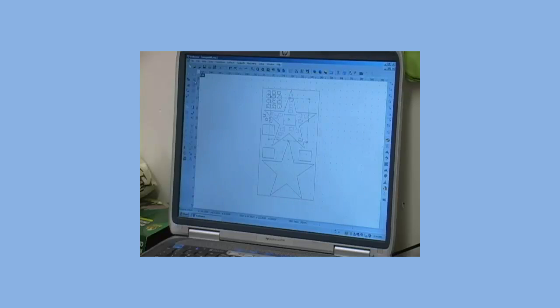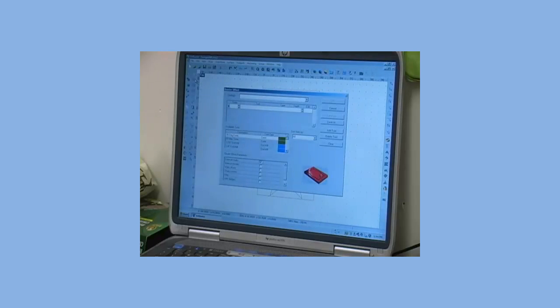We come up here to the top tool which says Routing Offset. There is an arrow that drops it down. We want to click the first icon, or the one that's actually seen anyway. Our tool selection comes up, and we're going to pick 1/4 inch end mill. Double click in the white space where 1/4 inch end mill is.